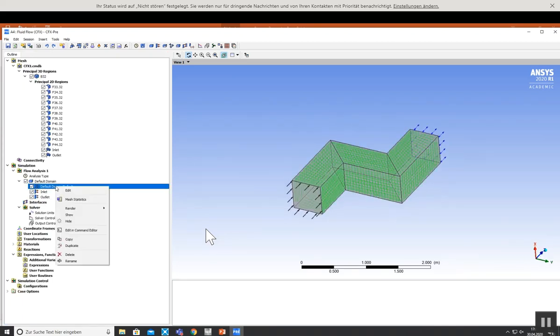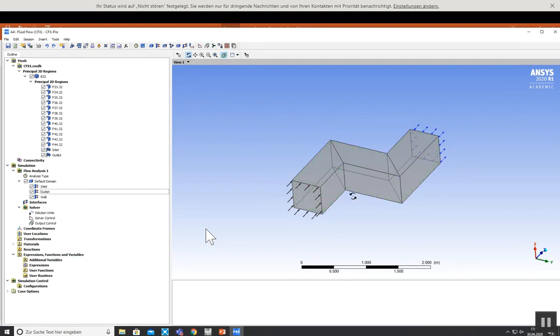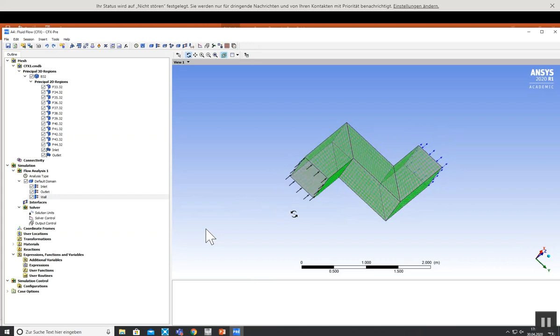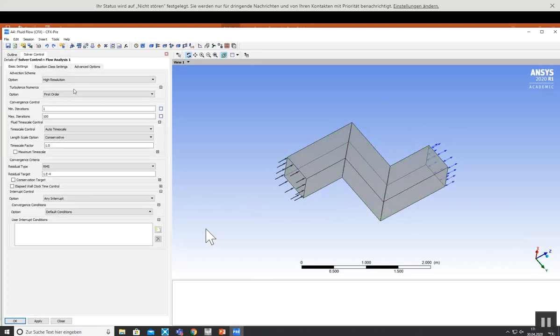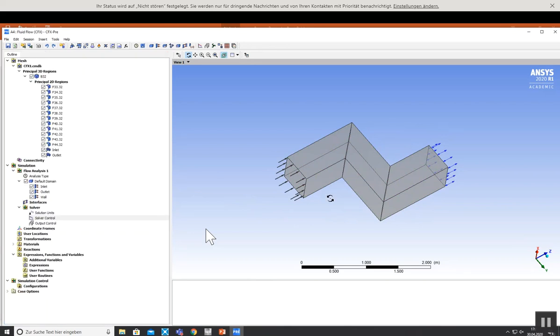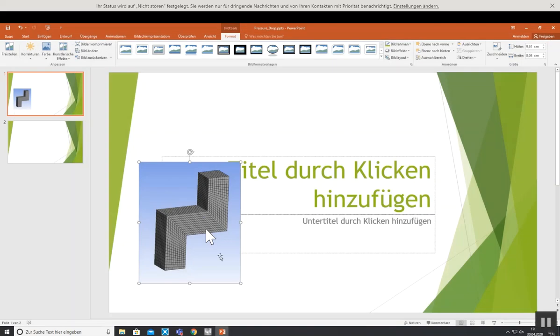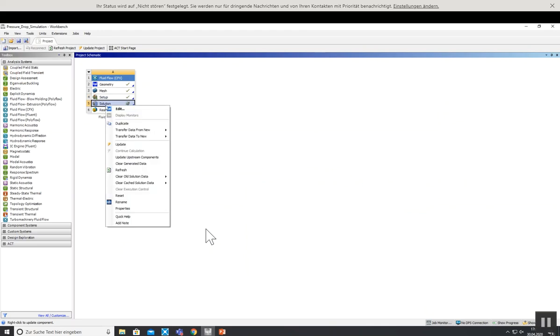Okay, and then I can rename all the other walls. Very simple. And I use smooth walls. So I want to set lambda to 0 later for the walls. Okay, and the simulation maybe go to 100 here to get comparable results. Okay, that's it. Perfect. We're finished. It should run. Give it a try. I hope the compiler will be fine.